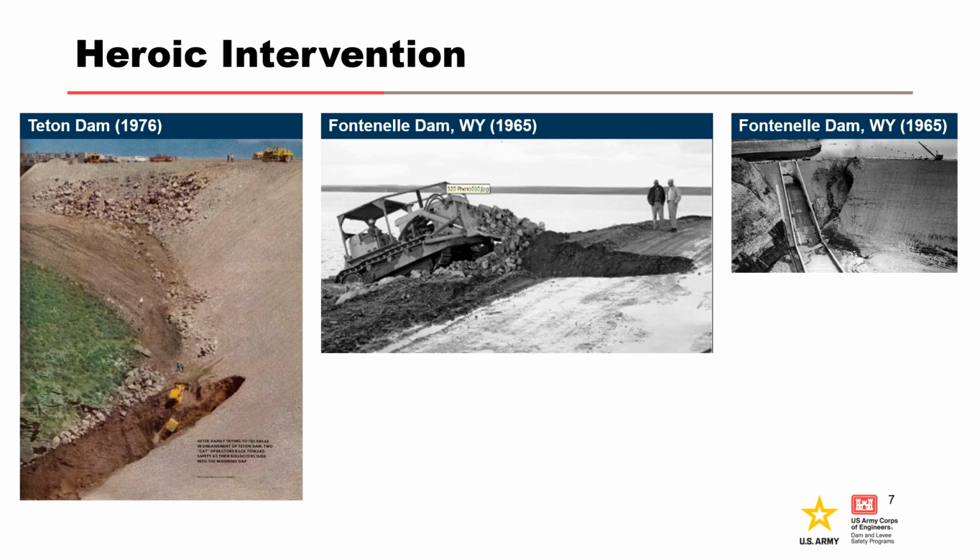While the reservoir was drawn down, the eroded portion of the embankment was replaced and the foundation was grouted extensively. Only 45 feet of embankment remained between a sinkhole on the crest and the upstream face. The sinkhole was filled with upstream riprap.